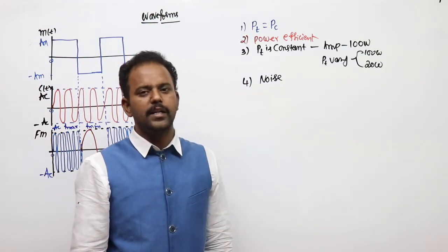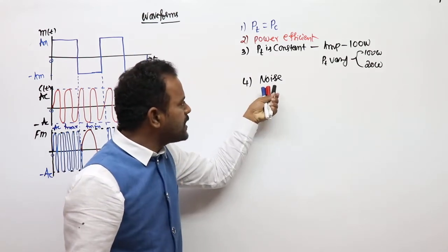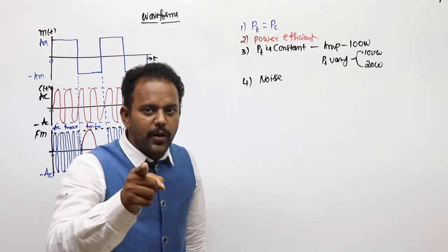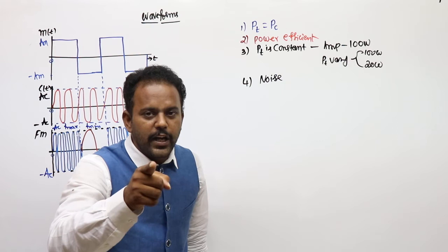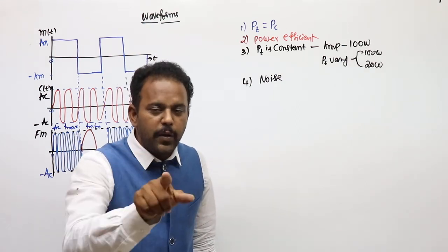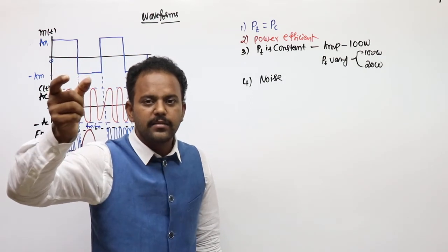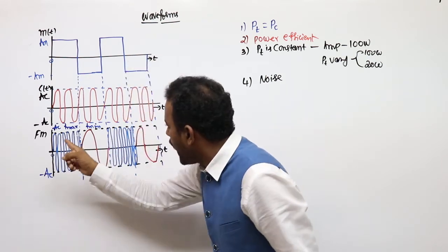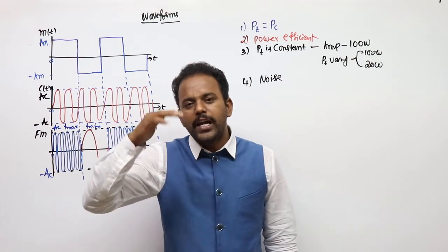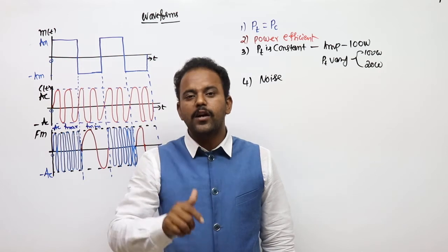And one more point, this is most important. If any noise is added to the amplitude of an FM signal, that noise is called AM noise. That noise we can clearly eliminate by using a double clipper circuit, and we know that any amplitude variations in the FM signal are only because of noise, because in FM the amplitude is constant. But in AM, if any amplitude variations come, we cannot recognize which is because of noise and which is because of the message.